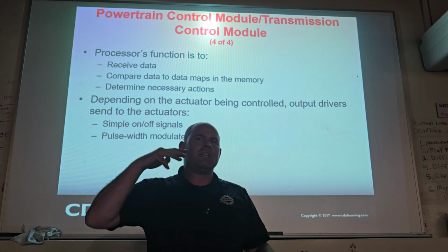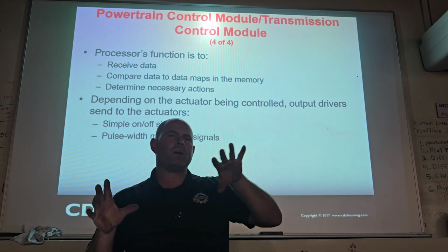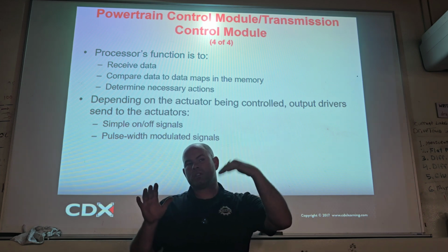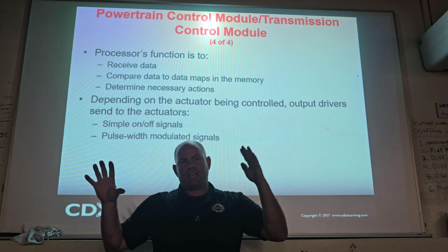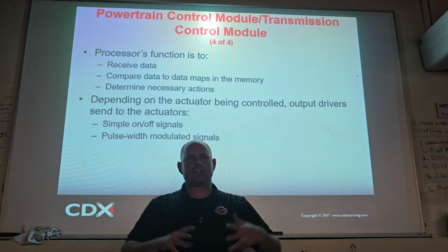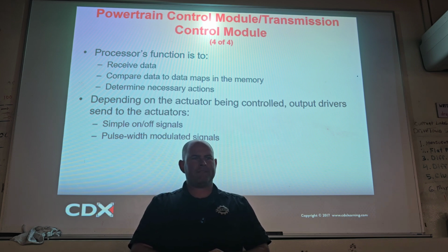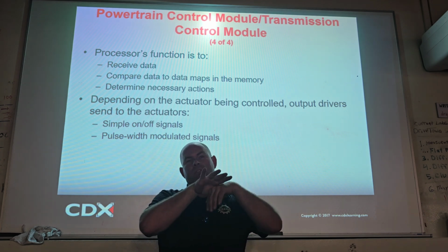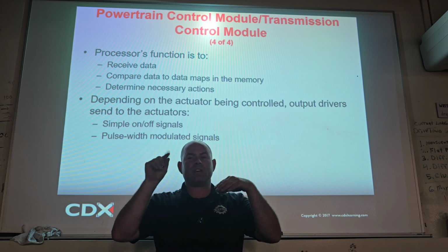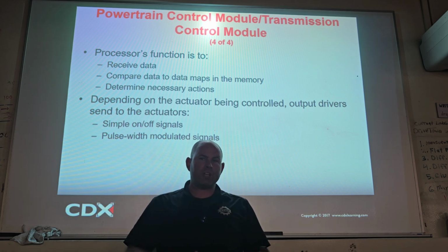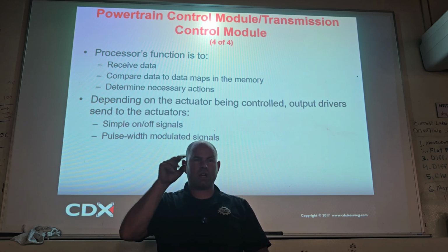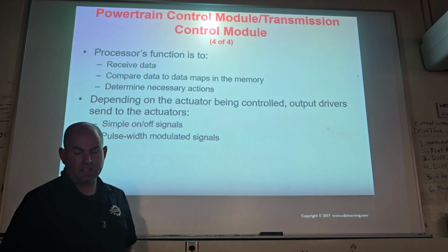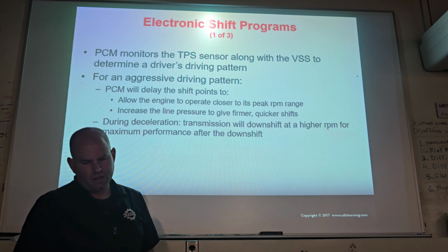So if a solenoid isn't working, it may be the solenoid, it may be the wire, but also remember, there are drivers, and those are basically transistors in the TCM. That transistor has to pulse ground to that SL1. If the transistor is bad, that's a bad driver, how would you diagnose that? Probably do duty cycle, I would say. If you did duty cycle and it was a flat line, and you did duty cycle coming out of the ECM and it was a flat line, and you even went in active tests and you tried to command it on, it was still a flat line, you got pretty good reason to believe the ECM is not running its driver, it's not pulsing its transistor. And unfortunately, we can't really service those. That's in the ECM or the TCM. Cool. So that's all in there.